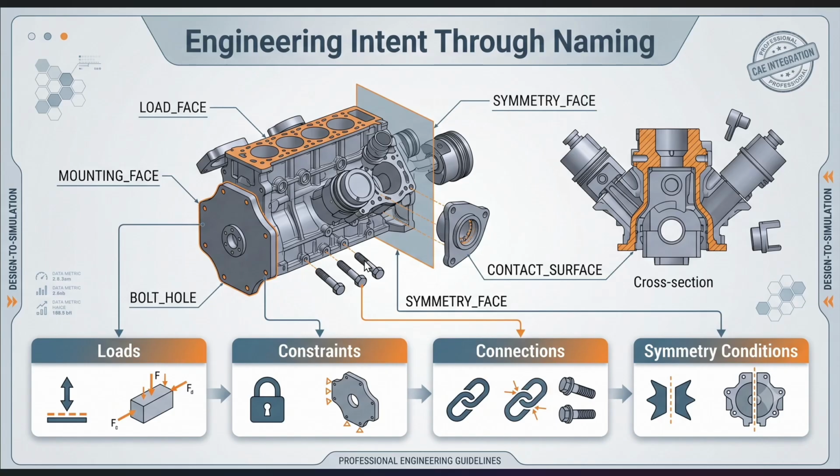And if you have to automate these things, you have to go with a consistent naming of it. So as soon as you make a product, you simply have to name it. Suppose this is a load phase, you mark it, this is a load phase. Even though your model changes, as far as your model is able to find a phase named load phase, it will apply load on that part. So this is the second reason why this is heavily used in industries.